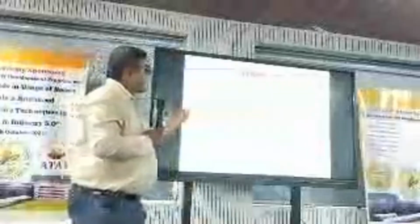So, some definitions: what actually is meant by driving frequency? Let us assume the engine is running at a certain RPM. That is the frequency, the RPM it is doing, called the frequency of the forced vibration. Let us assume my gas turbine is running at 3000 RPM or 10,000 RPM. That is called the driving frequency or the forcing frequency.